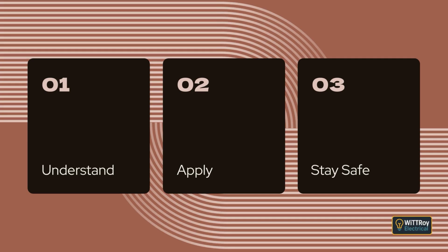Clause 3.11.5 Spacing from other underground services. Underground wiring must be separated from gas, water, stormwater, sanitary drains and telecommunications services by a safe distance. This distance depends on the type of service but is never less than 100 mm. The wiring must also be marked with suitable warning tape when required. Additional requirements apply for separation from telecommunications, gas and water services, as described in earlier clauses.